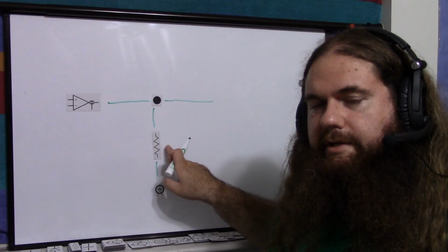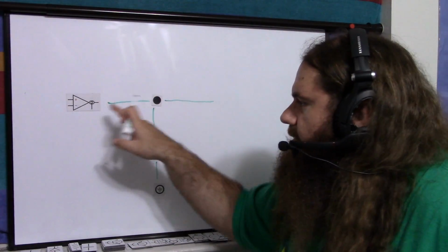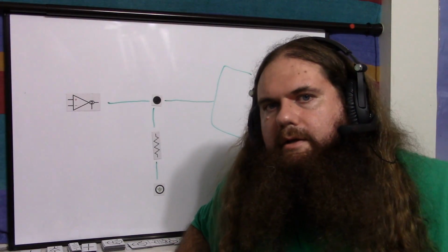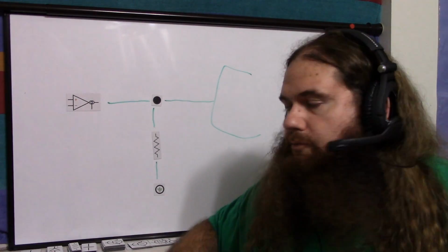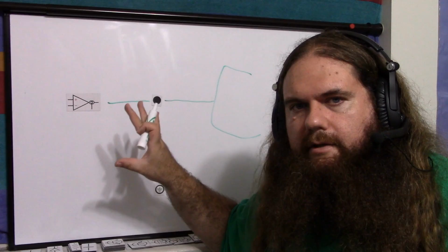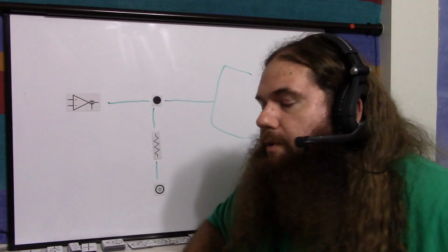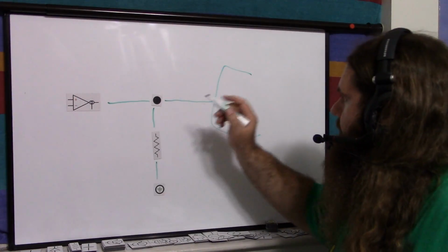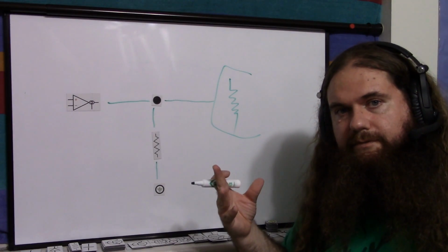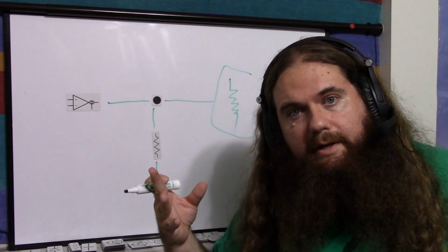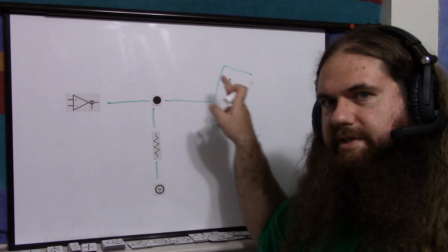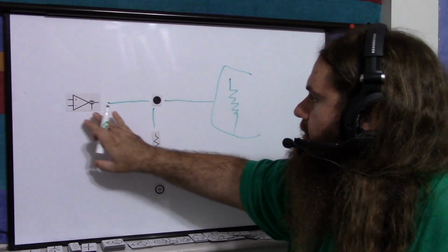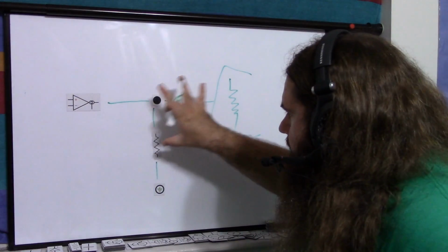Now the reason for the buffer is to make sure that this load value doesn't affect the signal. You could perhaps plug this directly into a chip. If that's just a microcontroller with an analog input pin, you might be able to just hook this up and read this signal if you wanted to do some audio processing analog style and then read the final result digitally. But not every microcontroller, not every ADC works the same way, and they might load the output. Because whatever effective resistance this has, it might be constant, it might not be. So if this is changing, you've got a parallel resistance here, which is changing the resistance overall, which is changing the signal, the voltage, because it's always going to try and put out the same current no matter what the resistance changes to be.